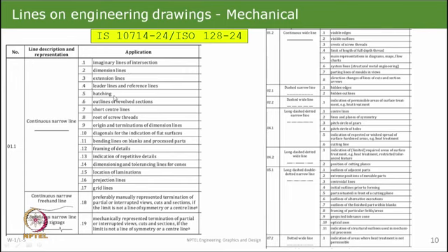Dimension lines, extension lines, you will learn all this as we go in the course, and it could be even this type of a line, then zigzag line which is still a thin line, and then there are lines which are continuous wide line. So, that means this is thicker. What all it can denote, what does a dashed line denote, what does a long dashed line denote, what does a dash and dotted line denote. So, like this there are many examples. As we go along in the course, we will use many of these.